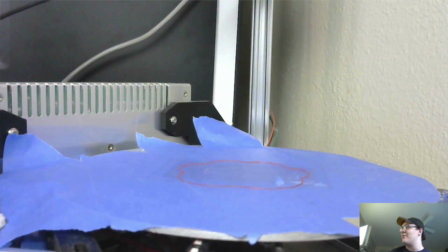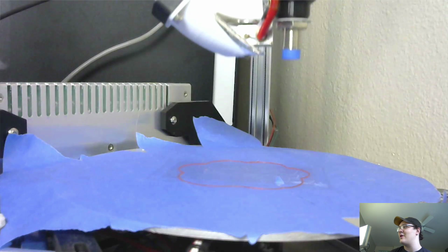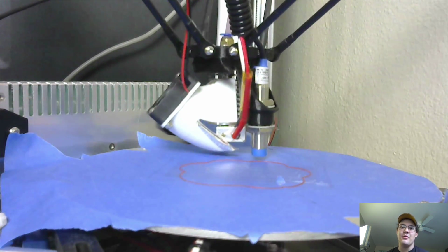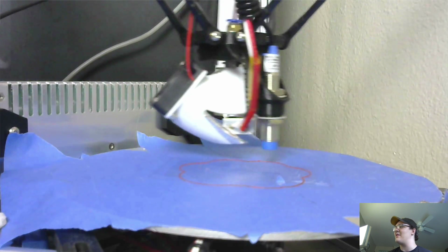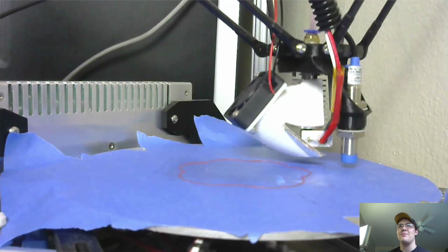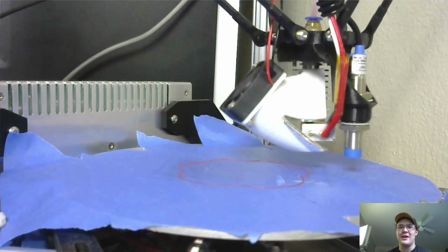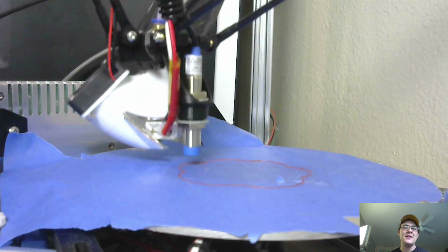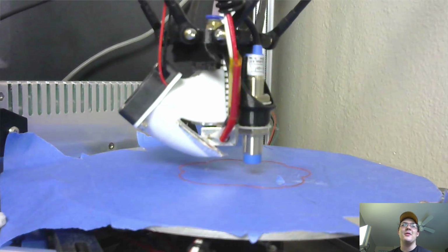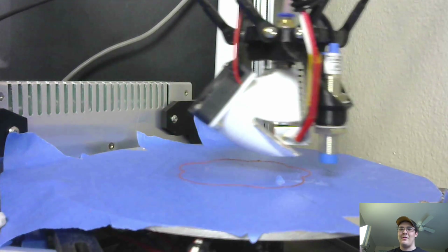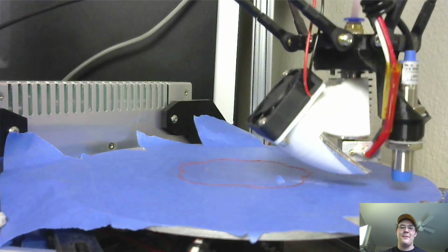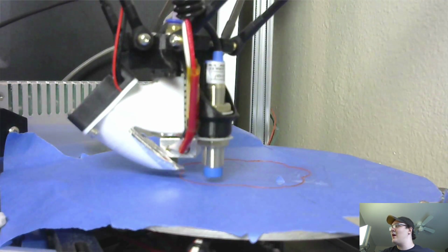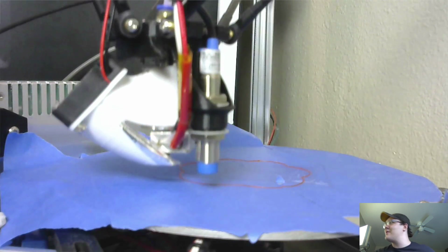Now you should see your printer go flying down towards the bed, and then a little bit before it should understand where it's going to be going. And it's just going to go through and probe all sorts of spots. The default for the Kossel that Folger Tech gives you seems to probe like 38 times. It's got a 7x7 array that it has to fill, but of course it's not able to go out to the farthest extents on the sides of the circle, just because circles. Don't worry about it, I'm rambling. Anyway, it probes like 30 some odd times.